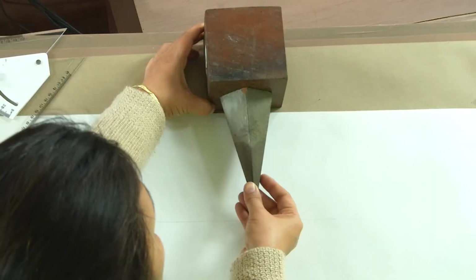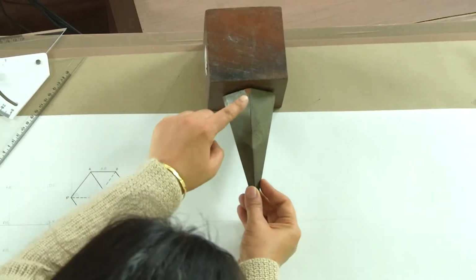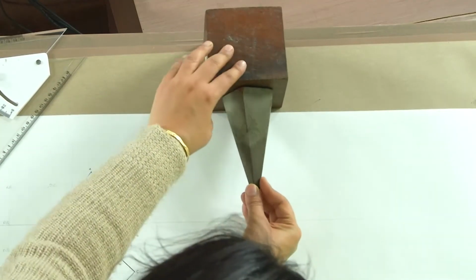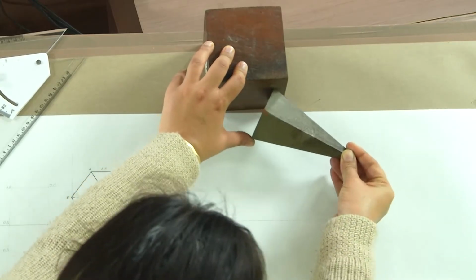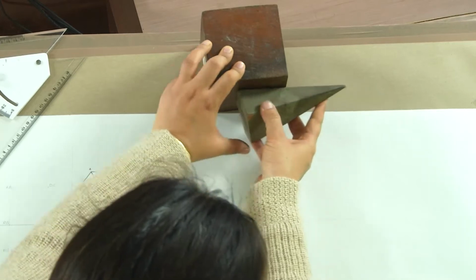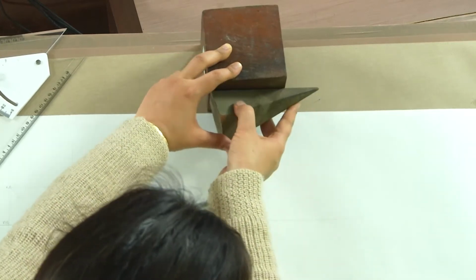So, what will be the initial original position which we can start with? We can start with having the pyramid perpendicular to VP, where we will see the true pentagon or the true shape of the base, and then we incline it in such a manner that this face is now in VP.